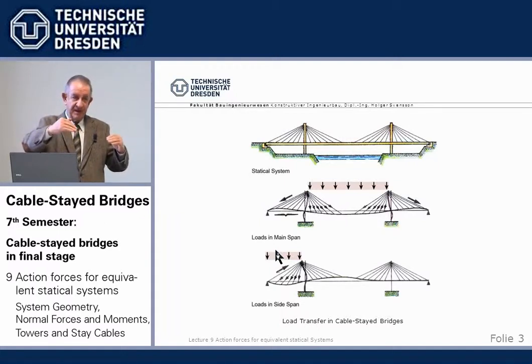So it becomes clear we need a certain minimum amount of forces in the backstay cable, so that if we get the compression from the side span loads, the slack of the backstay cable doesn't become too big, the effective E modulus must not be too low. But we understand we carry compression in the backstay cable by a reduction in the tensile forces from permanent loads.